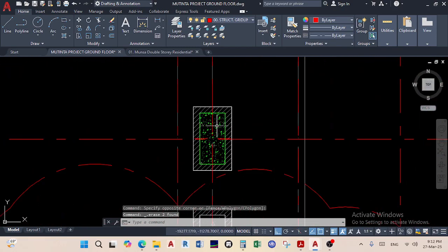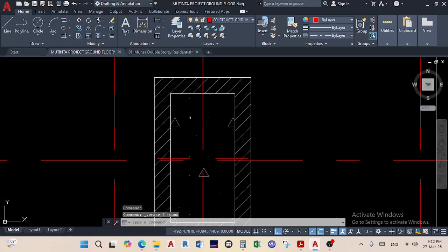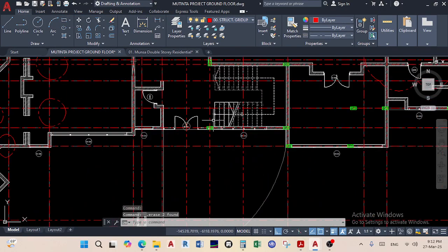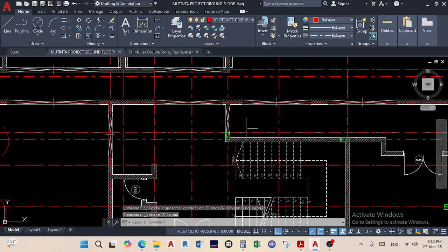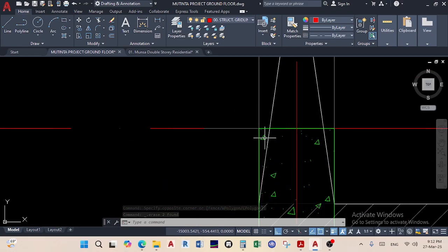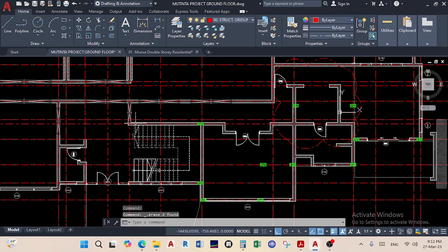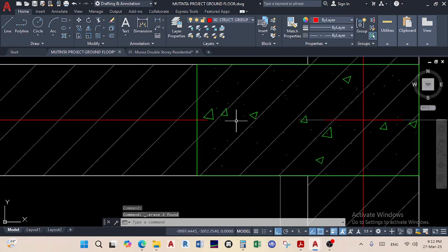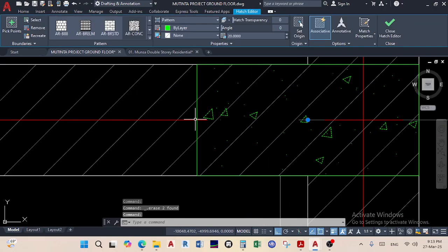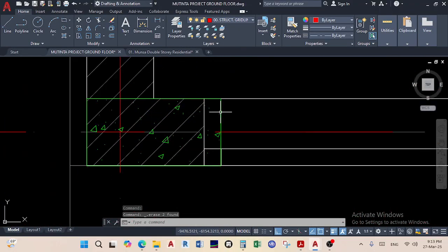So you're practicing separately, and you're placing these columns separately from the way that I'm placing them. It's okay, it's accepted. You do not necessarily have to do exactly what I'm doing. For me, I'm using a certain level of experience, and I'm trying to accommodate my slabs. I'm trying to make sure that most of them will be two-way slabs, and I'm thinking of my beams. I do not want them to span over long spans because the shorter the spans, the more stable the structure.